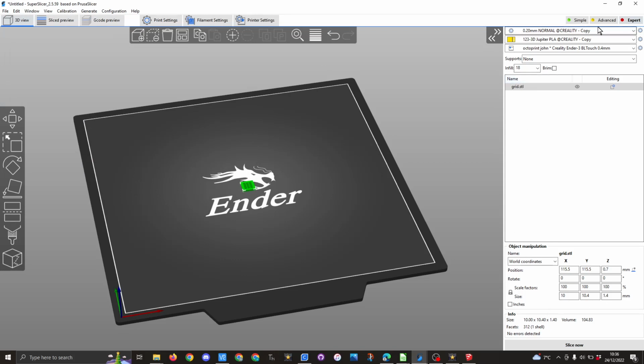Obviously depending on your settings that you want to use to print it, I would possibly print this at 0.2. You might want to take it down to 0.1 layer heights. Infill, that's up to yourself what you normally like to have yours set at. You might want to experiment, but these I have printed out using this model, the STL, and it works fantastic for me. So I hope this helps you learn how to do some very quick and easy things in SketchUp Make for your layout.